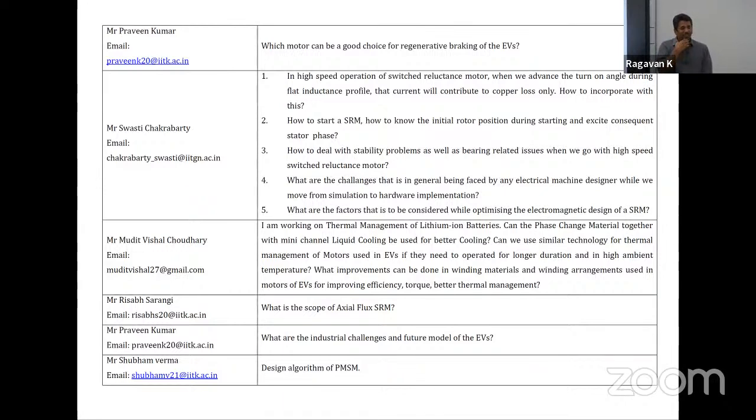So we actually have a few patents that we have filed and been issued where we had quasi sensorless methods that allowed us to use a notch on the shaft that combines with the current profile that we are getting. So there are ways to do that, but if it's just talking about initialization, a lot of times in the lab setup, you would do a hard alignment. So apply current, it aligns itself.